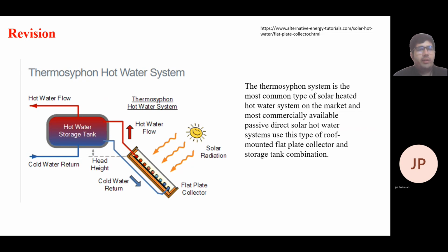Basically, due to temperature difference, the cold water has more density as compared to the hot water. So the hot water will move upwards as compared to the cold water due to lower density. In this way, without any pump, without giving any energy, in a natural way, using basic convection and heat transfer, we can run the system. It's called a thermosiphon hot water system.